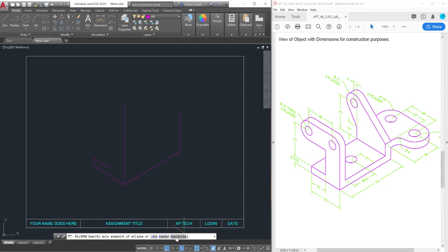You're going to see a big difference here now. So I'm going to select this. I'm in my left plane, so I'm going to pick this point here. And now you'll notice I don't have to figure out what the minor and major axes are for this ellipse. AutoCAD knows I want to draw a circular hole in isometric view with this thing called an ISO circle. So now I can simply type in the diameter if I invoke the D option and give it a value of 10. So now that is the correct size for here. However, it's in the wrong location. That's easy enough to fix.